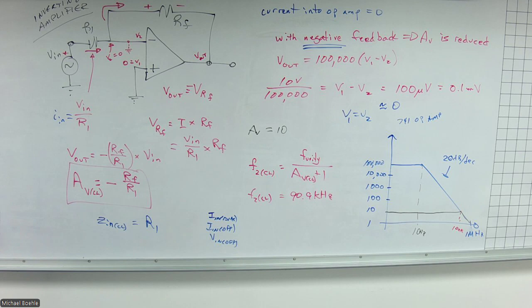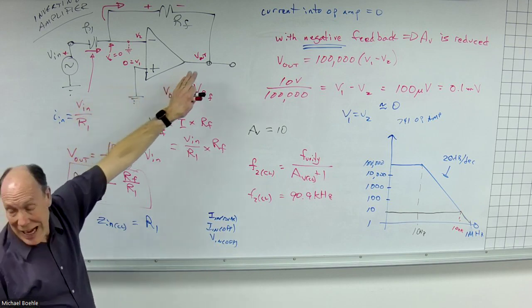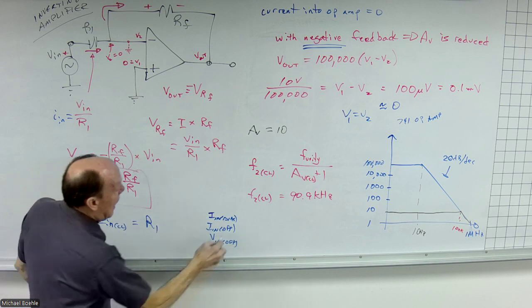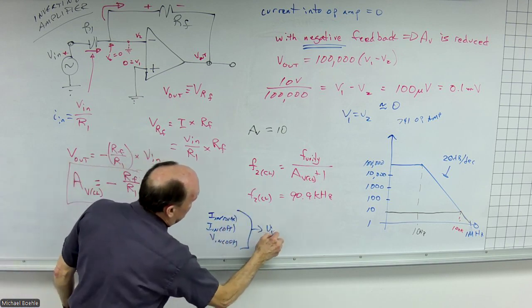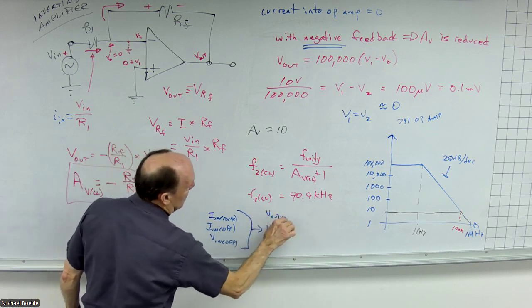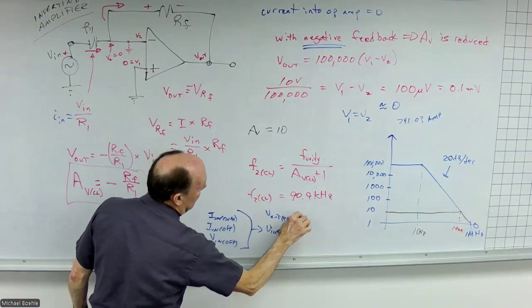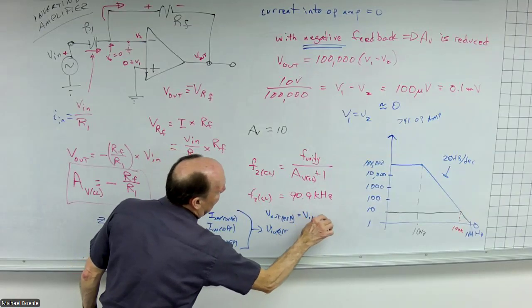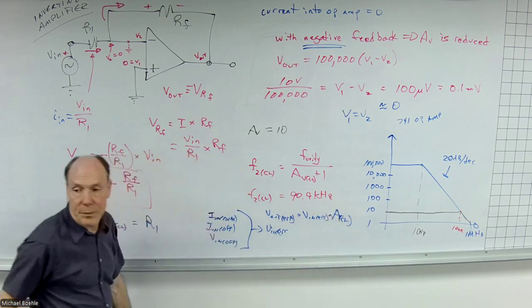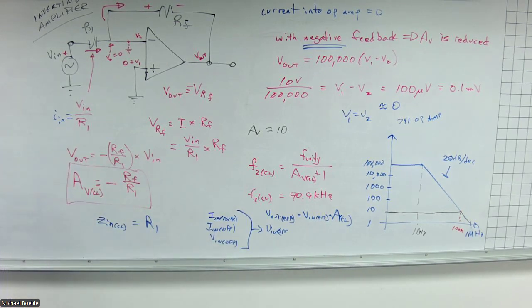But by using negative feedback, the input error to get your output error is going to be whatever that input error is times that closed loop voltage gain. So now if I've got an input error that adds up to a few millivolts and my gain is 10, well, now it's only a few tens of millivolts. Another advantage.